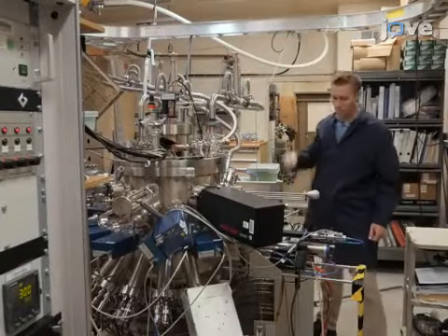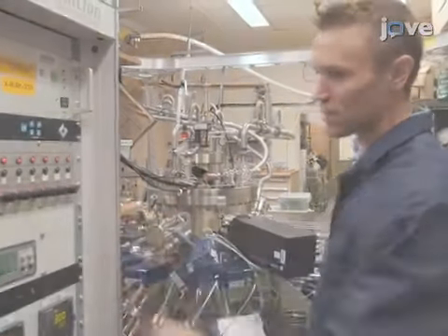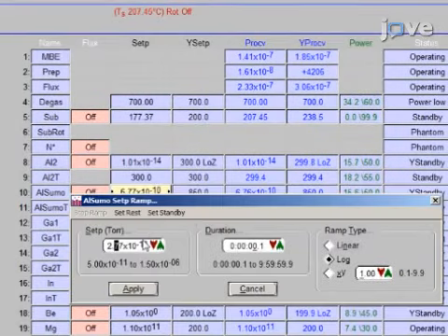First, ensure that the cryo panels are cooled and that the growth chamber is at base pressure. Ramp up the effusion cells to their beam flux measurement temperatures at the proper rates and wait 1 hour for the cells to stabilize.